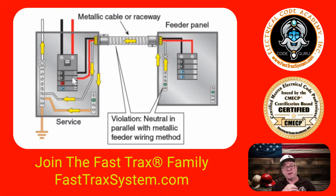Although UL 1569 already standardizes the equipment grounds for whatever the amps are of those conductors and whatever breaker they would be terminated to. So you really don't control that with an MC cable. Although you can order MC cable with an oversized equipment ground if you want. It's just going to be a lot of lead time and probably going to cost you more. So off the shelf MC, the equipment ground's already going to be sized for you.